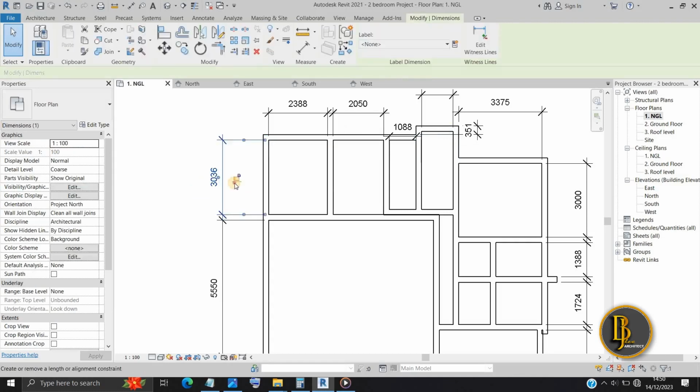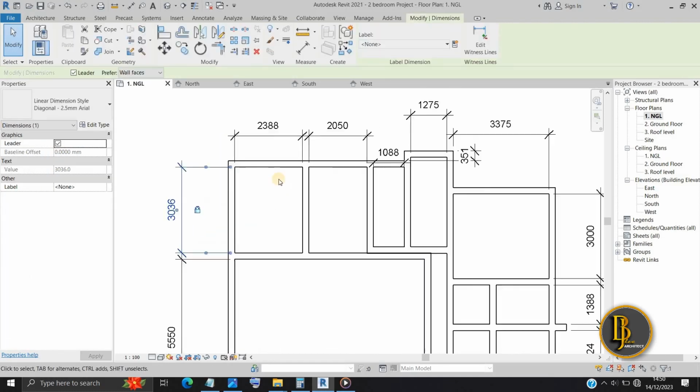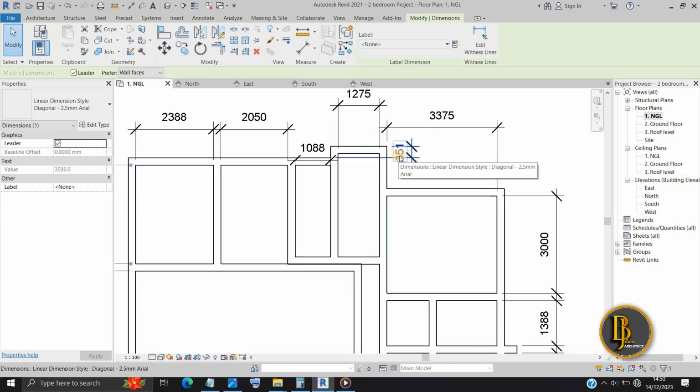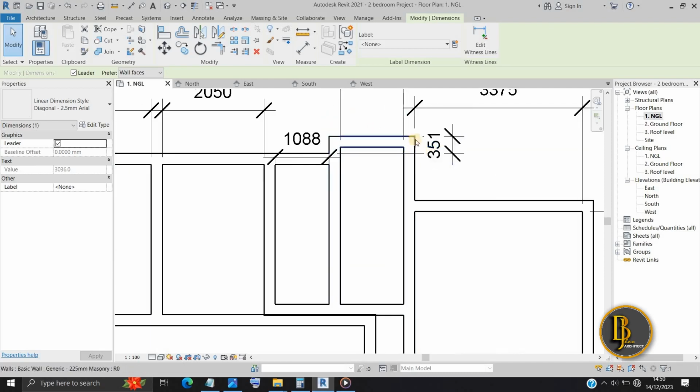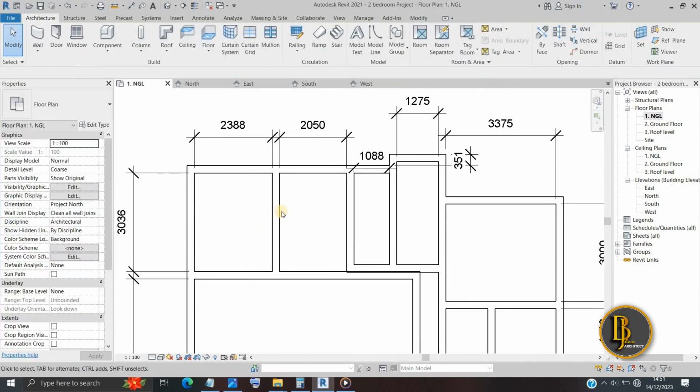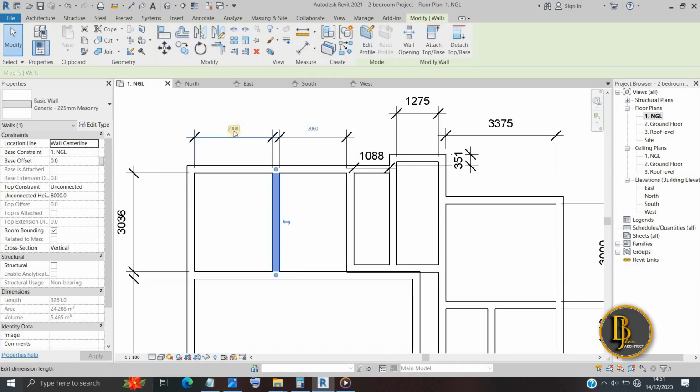So you can as well lock dimensions. Let's do the second one. Remember this particular one was 1300, but because this one has shifted, this dimension has shifted up. This one has changed to 3531. It is dimensioning from this top to this top. DI. Let's check again, from this top to this top. Remember previously it was 1300. The dining area: if you want to shift this dining board and make this 2500, you click here and it will highlight dimension. These two will highlight, but we are trying to shift this one here. You are shifting it to the right hand side.